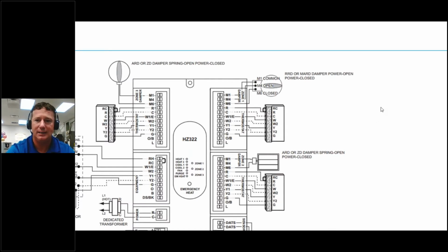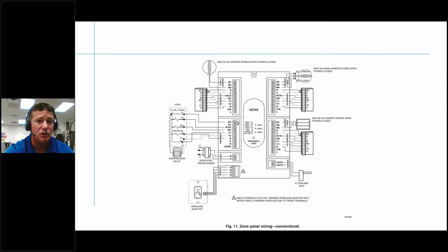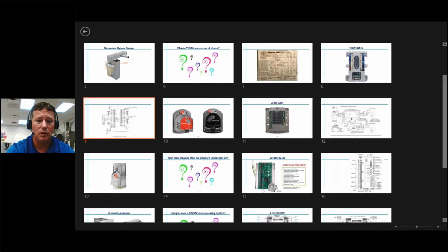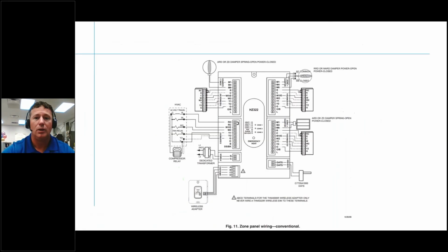That's fine when we're talking about pieces of equipment that haven't changed much over the last 30 years. We're talking about a zone control that works great on a conventional PSC or potentially an ECM constant torque based motor, where we're having major effects of high static pressure, and we're not communicating. Because remember, this is all legacy control. So this works great for a single or two-stage gas furnace and a single or two-stage AC or heat pump.